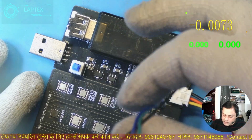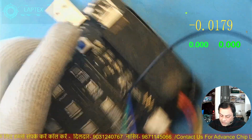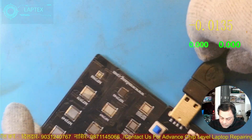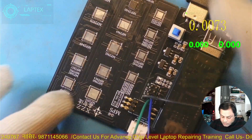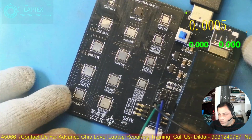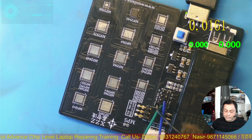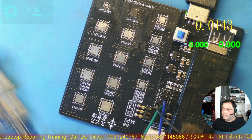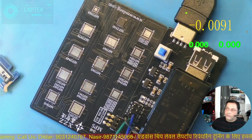I have injected it. I was trying to take a backup, unfortunately I don't have a heatsink, otherwise I could have tried. Inshallah, in the next video we will try, because if the voltage is not stable, we cannot do it online. Online means on the live motherboard, you can inject 3 pins: ground, SDA, SCL, and you can read the data of the MPS IC. Okay, so now